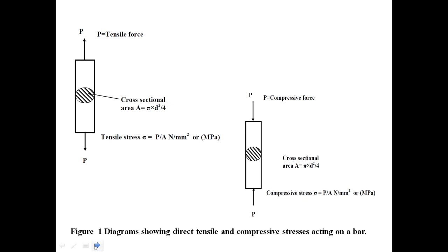In case of ultimate tensile strength, this property is not used for design calculations for a ductile material, but for brittle material, ultimate tensile strength is used for design calculations. In case of ductile materials, yield stress is used because a machine element made with ductile material should not be exposed up to yield stress. Therefore, a safe stress is arrived at by incorporating a factor of safety value.